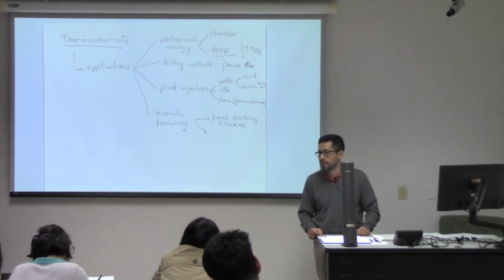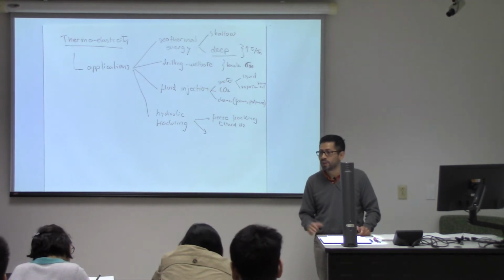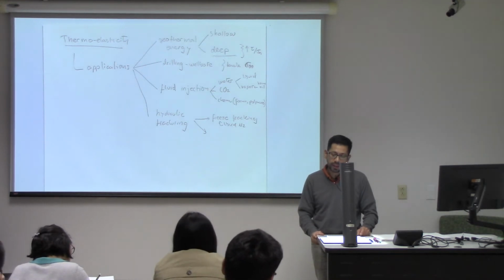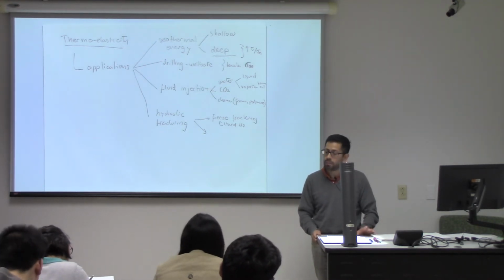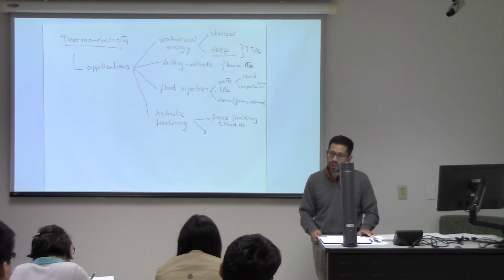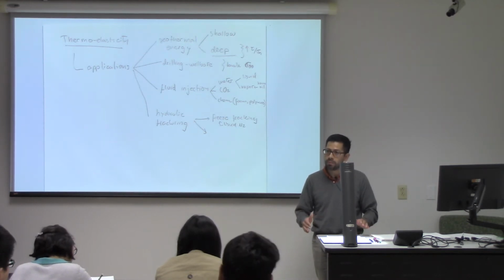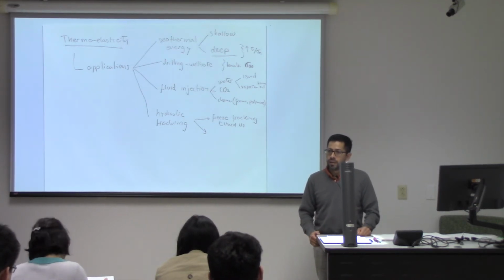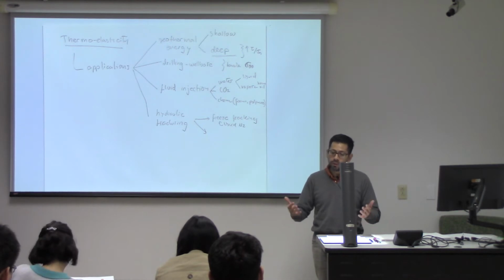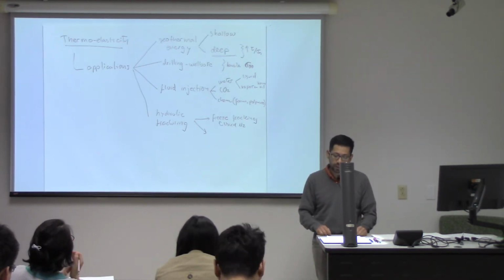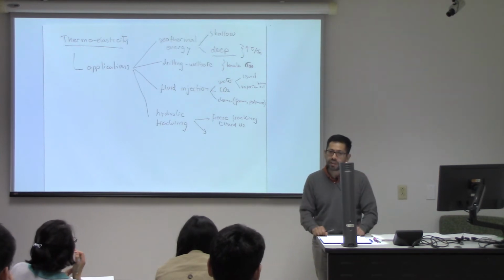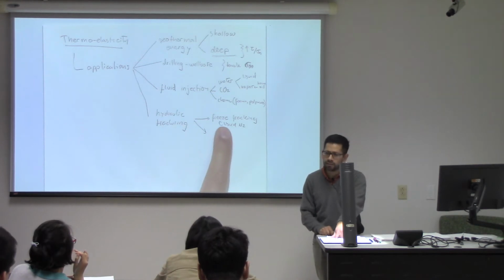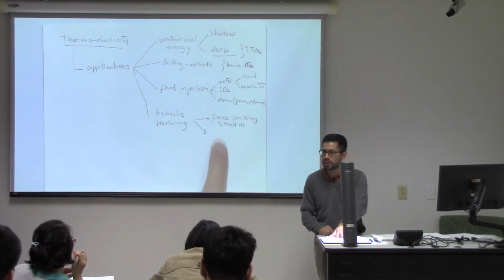Conceptually, that kind of makes sense, right? Practically, it might not be as easy as one may think, but conceptually it makes sense. So you lower the temperature and create lots of tensile stresses so that you have a hydraulic fracture. In general, or more scientifically, these are called fluid-driven fractures because the fluid is opening the fracture. Well, in this case, you may have fractures that are not opened by the fluid, but are just opened because of the temperature.